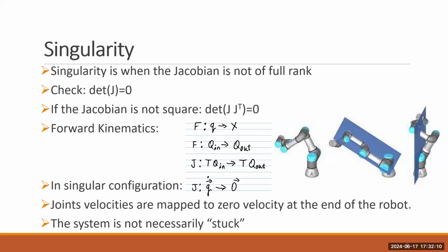Any questions about this? Did you learn this before? No? If we say my arm is like a robotic arm, if it's fully stretched, I cannot provide velocity in the direction in and out. Like this, I cannot provide anymore, because any movement will move it up, down, or sideways. My arm actually is not in singularity because I have redundancy.